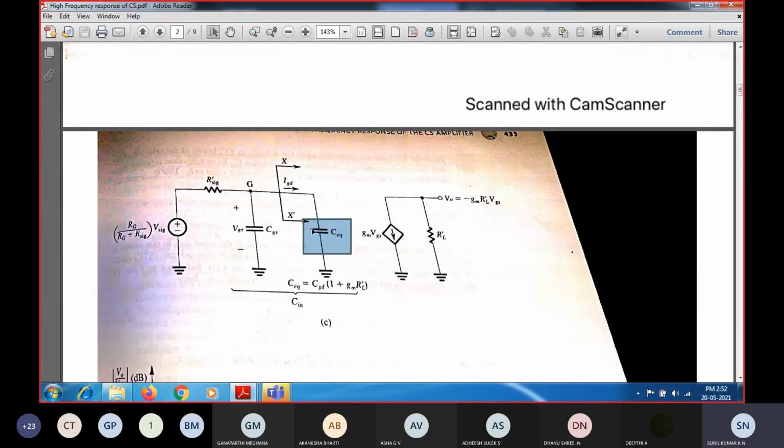Now, the equivalent capacitance connects between gate and ground, and if I consider the output side, drain and gate would have another output as well, but since it is not required, between the gate and drain, if I add one capacitance, you should listen carefully. It has to be connected in such a way that the current drawn by the equivalent capacitance must be equal to the current that is flowing between the gate and drain. If I obtain that, then we can easily convert it into a single time RC constant.